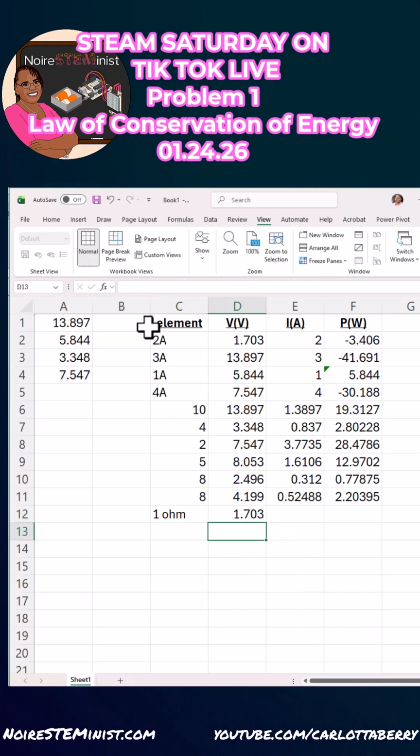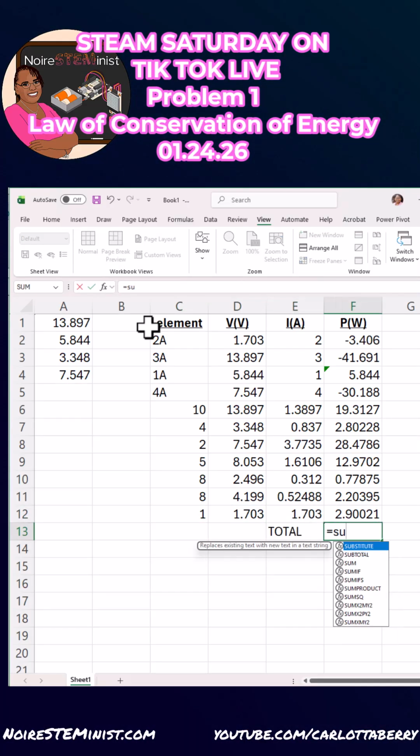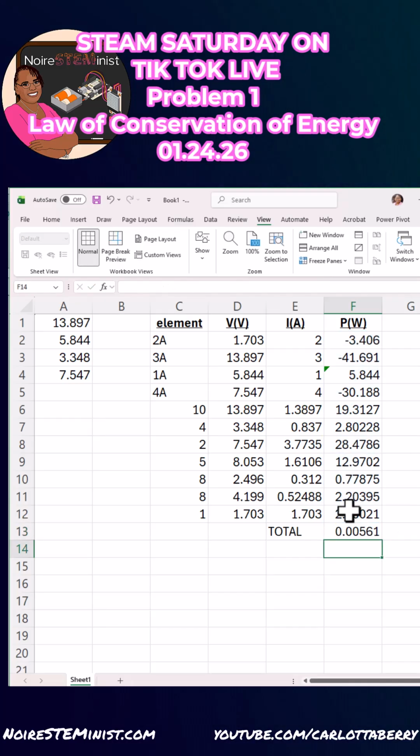And finally, the 1 ohm resistor, the voltage there is V4 minus V2. The current is 1.703, and it absorbs 2.9 watts. I find the total, and it should be 0, and it is, except for a little bit of rounding error. So this obeys the law of conservation of energy.